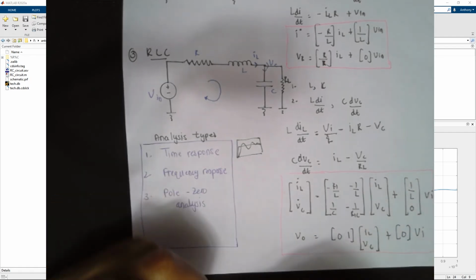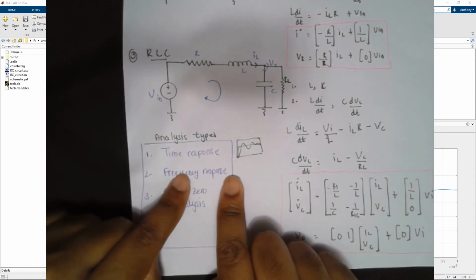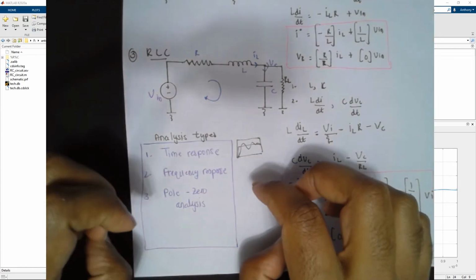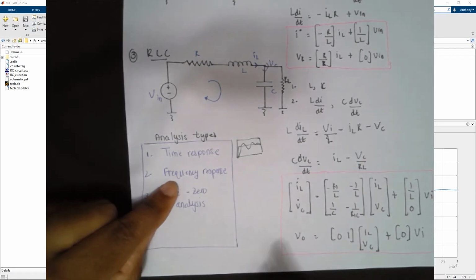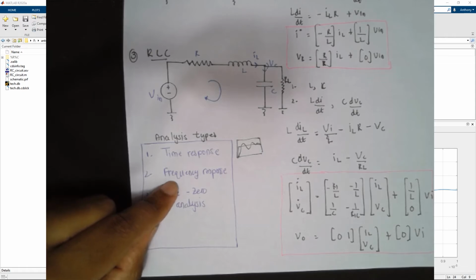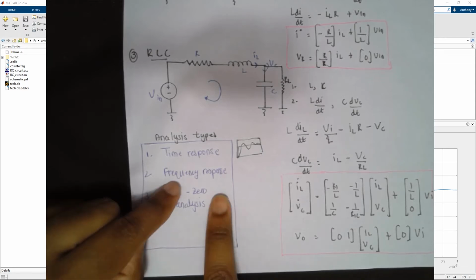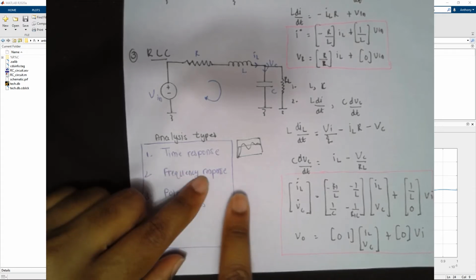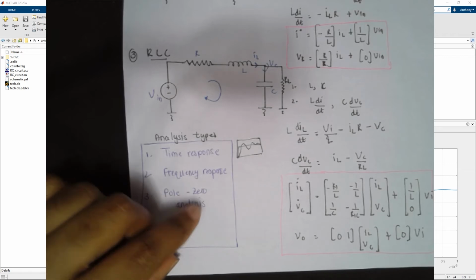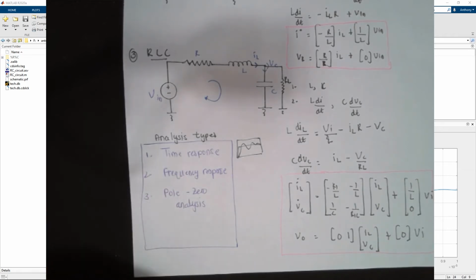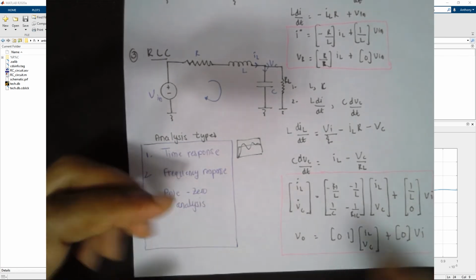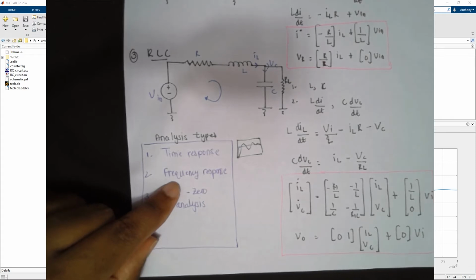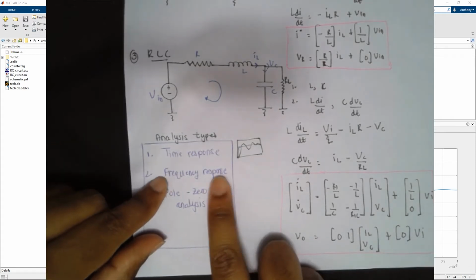The second is the frequency response, and I'll show a little bit about it shortly, where you can see the phase and the magnitude of the circuit. A frequency response takes a sweep from say 0 hertz all the way to however high you want, 50 kilohertz, 50 megahertz, 50 gigahertz. It shows you the magnitude of the system, whether there'll be a phase lag, and how it responds as the frequency changes. So it basically does a frequency sweep and models the circuit and its behaviors.